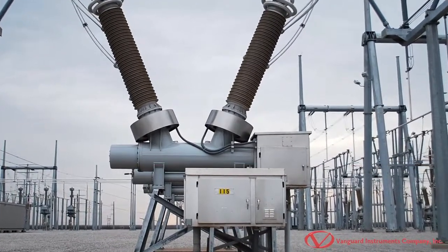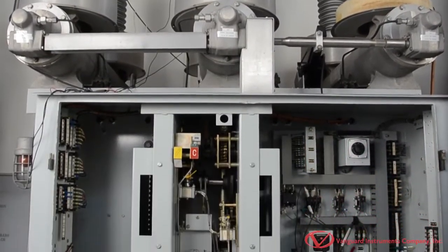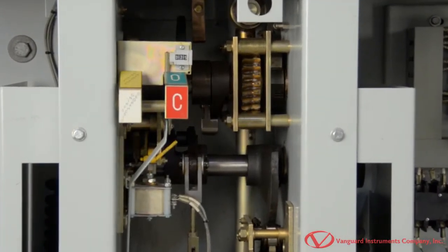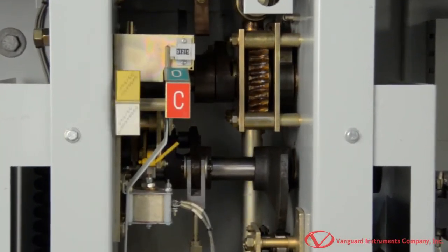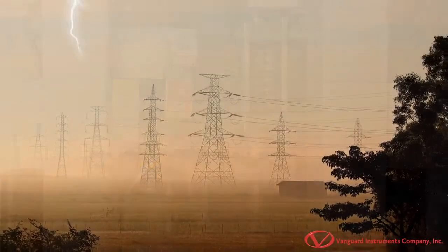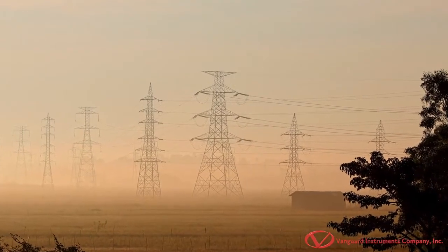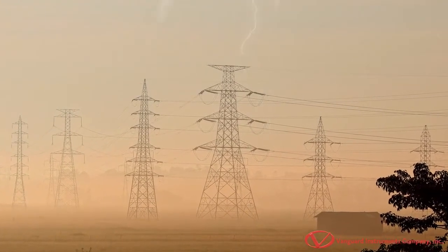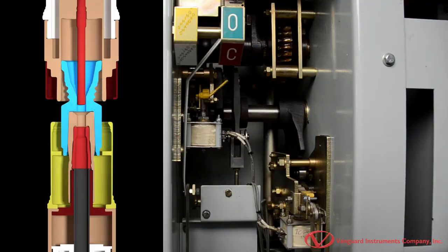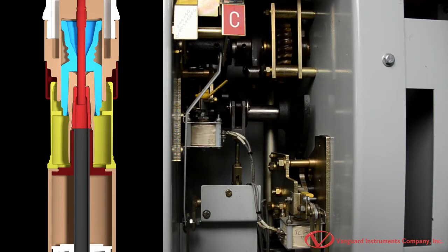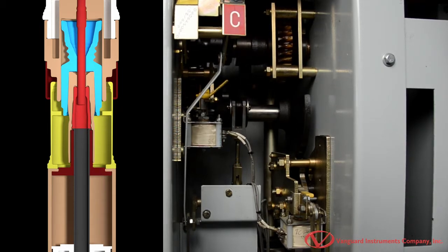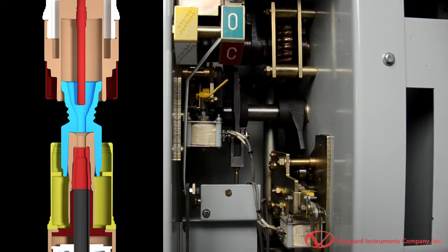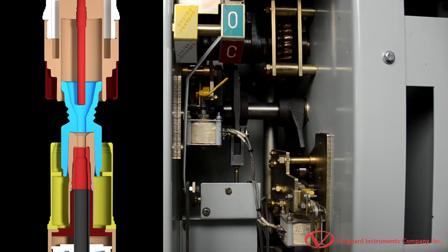Circuit breakers are an important and critical component of the power delivery system. They are mechanical switching devices capable of making, carrying, and breaking current in normal and abnormal conditions. During abnormal conditions, such as when lightning strikes a transmission tower, circuit breakers isolate the faulty components of the system to prevent additional damage. Ideally, in the closed position, a circuit breaker should act as a perfect conductor to ensure optimal current flow. In the open position, an ideal breaker should act as a perfect insulator and should be able to break the current instantaneously.